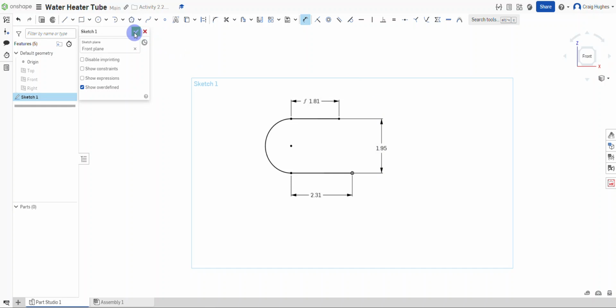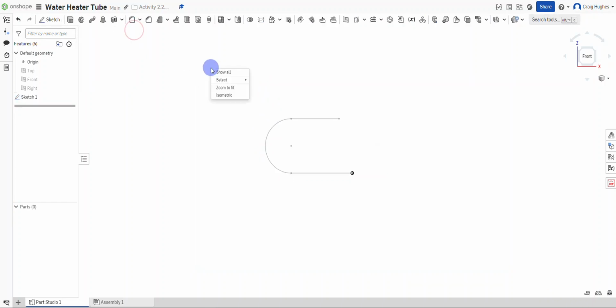Let's finish that sketch. When we did the arc on the fly, these should be tangent. So actually what I can do is escape dimension. If I need to, I can click and drag, or you can look over, and the little tangent icons will show up if we hover over those. If they don't, then you can always apply a tangent constraint between the arc and each line on top and bottom. Let's finish the sketch.